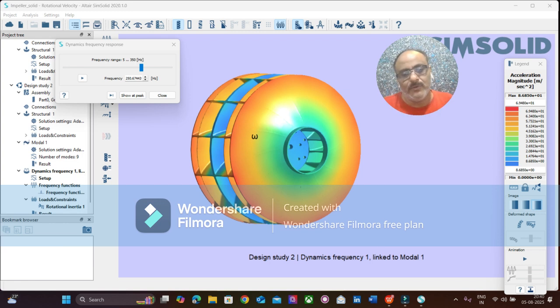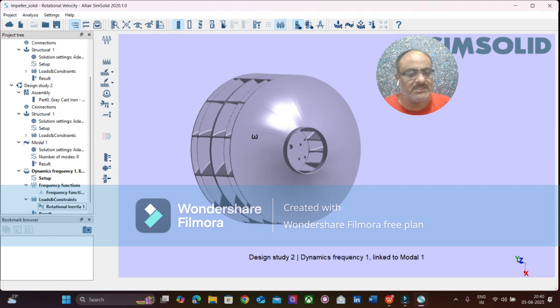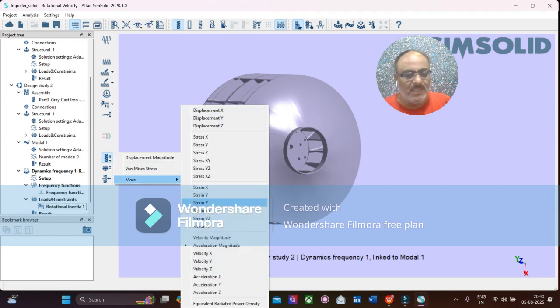We need to do some additional modifications. We need to brace it with additional stiffeners, or increase the thickness of certain members, the plates, the top and bottom stiffeners, or look for an alternative option such as reinforcing the collar. So we need to understand a lot of other things. Now let's study the other results.